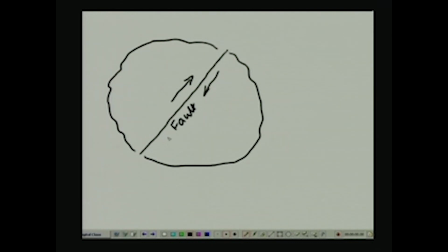So in this case, the principal stress in the vertical direction actually is going to be 0, because the rupture is taking place at surface, and the two principal stresses in this case are going to be aligned in this direction, and we are going to look at the configuration in greater detail later on in this lesson. So this problem is essentially a plane stress problem.